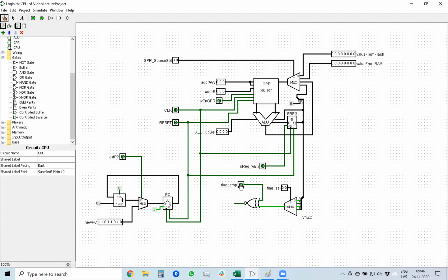So if we want the flag to be high, and it is high, for example, we select carry flag 0, they are equal, so this thing outputs high, so it's true. So we need to force jumping. And if they're opposite, if, for example, we want the flag to be high, but flag is actually low, then this XNOR gives us also low.